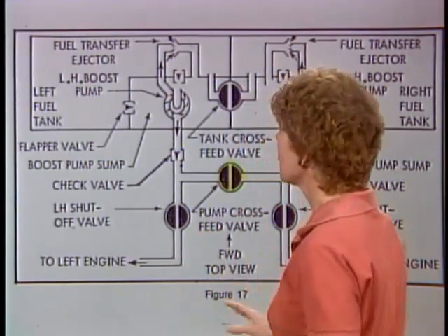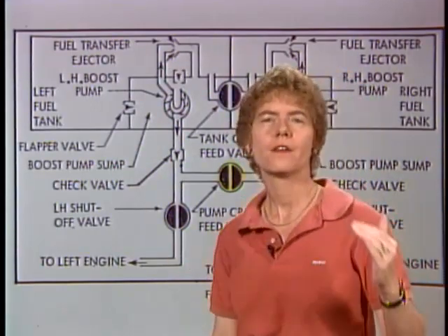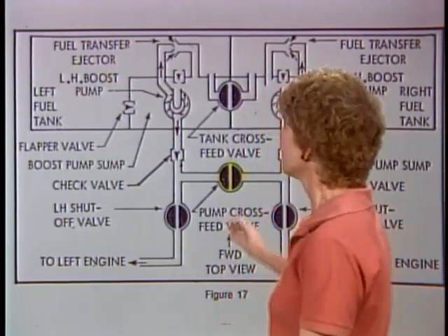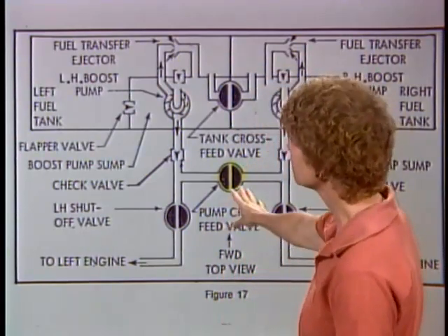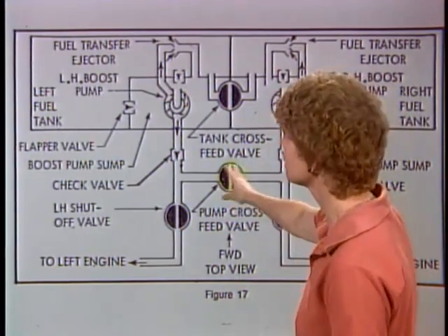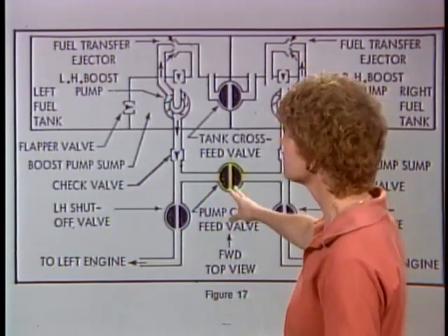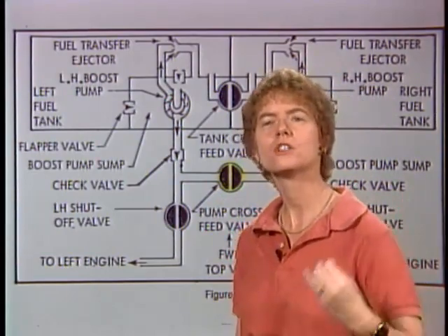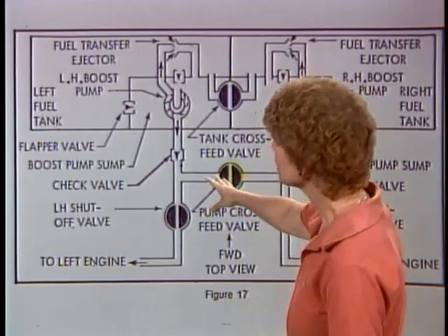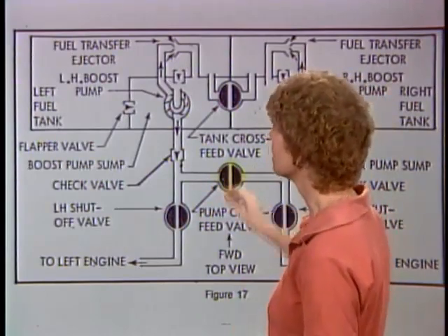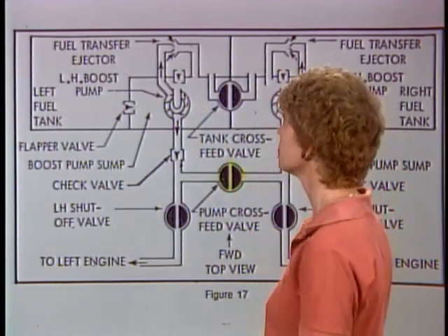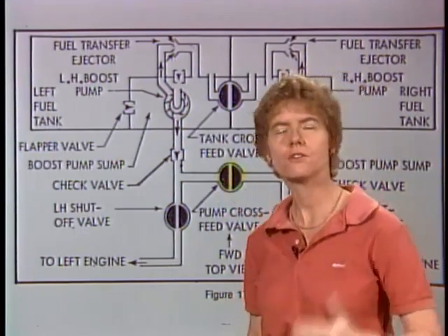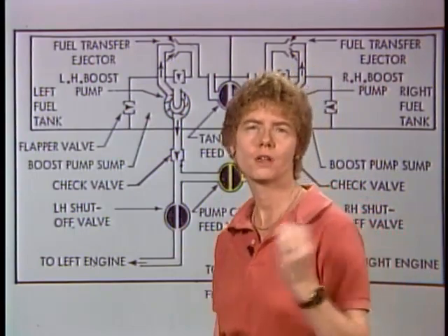Now, there are various valves in this cross-feed system, and they're going to ask you what the purpose is of the pump cross-feed valve. There is a tank cross-feed valve, and then down in the center of Figure 17 there is a pump cross-feed valve, and the purpose of the pump cross-feed valve is to allow the operation of both of the engines from one tank. This cross-feed valve is not to allow you to pump fuel from one tank to another. That's what the tank cross-feed valve does, but the pump cross-feed valve allows you to operate both the engines from one of the tanks.